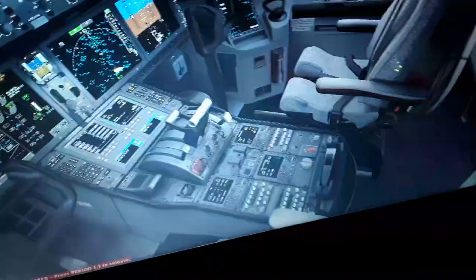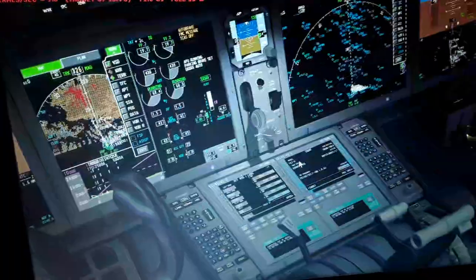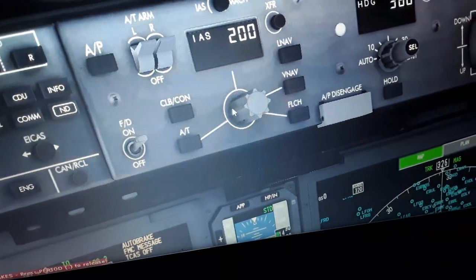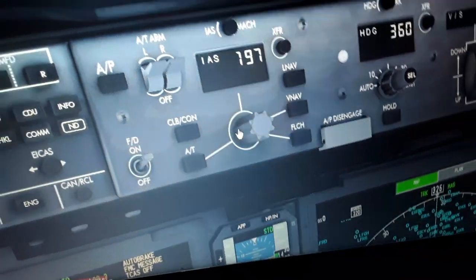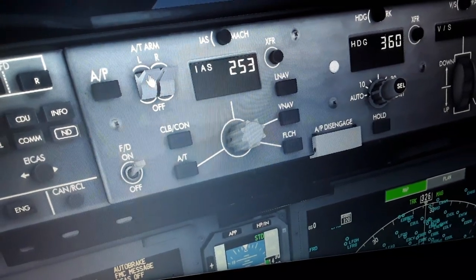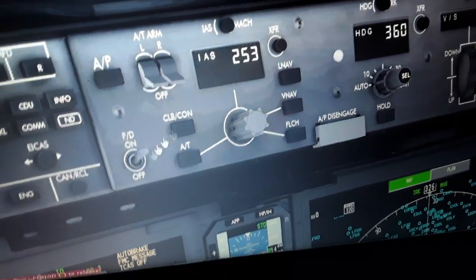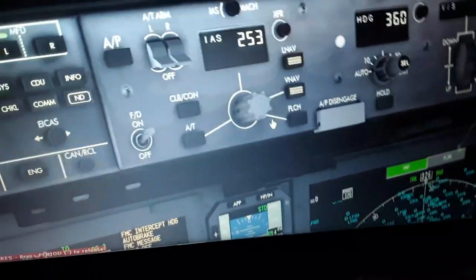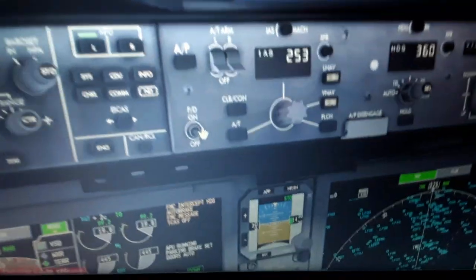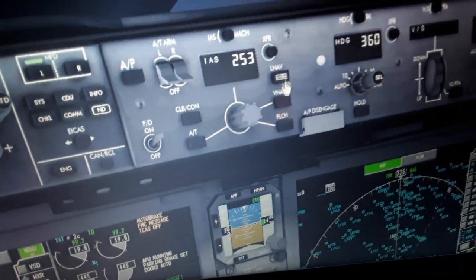So we use flaps up like this, 2, 3, 5, 6, speed brakes arm, and we set the autopilot before flight. You will see now the autopilot of the aircraft. So we have auto throttle left and right, the airspeed we can set whatever value we need. We set for takeoff. So here is auto throttle left and right, or flight director. The LNAV and the VNAV from the flight management computer, you will follow the flight plan. So we turn off the flight director, we will disarm the modes, we need to rearm them.